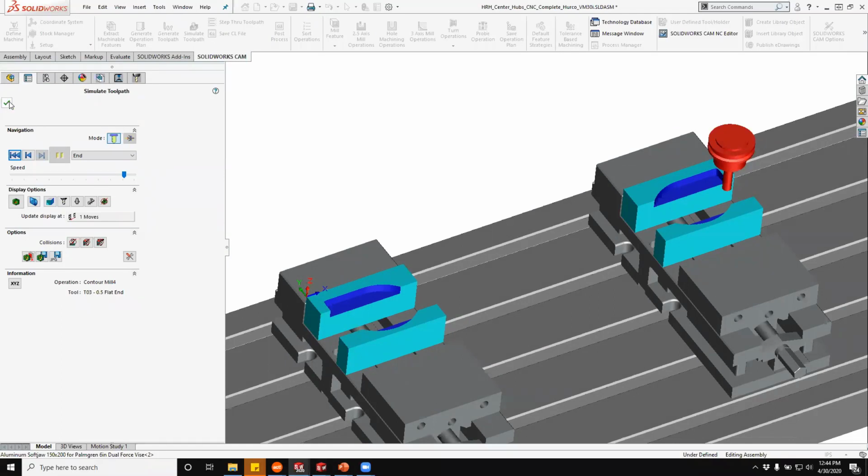But for me, if we talk about what we get with SolidWorks CAM Professional? Well, with CAM Standard, we said we get 2.5 axis plus milling, so some light 3-axis, and that would include a Z-level rough, Z-level finish, that combination cycle that we saw, and then also flat area machining.